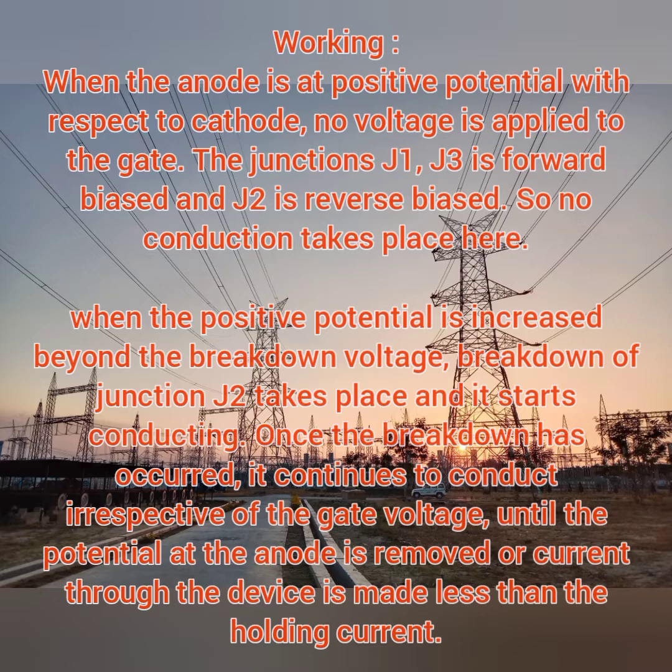So until this potential of your anode is removed or the current flowing is cut off, the conduction will take place. In order to control it, we need to give a controlled voltage. So in this case we are coming up with the gate voltage controllers.